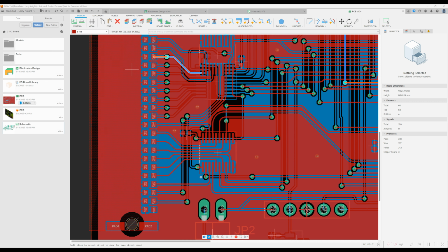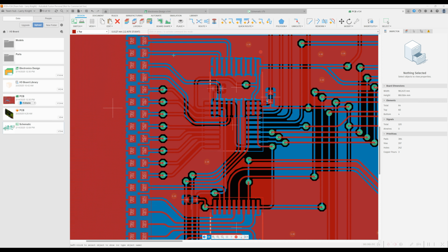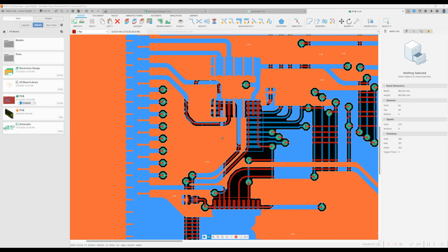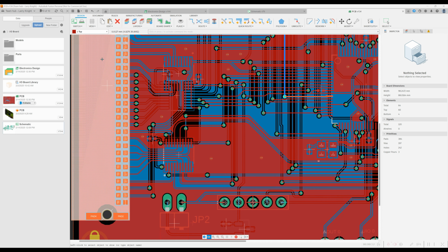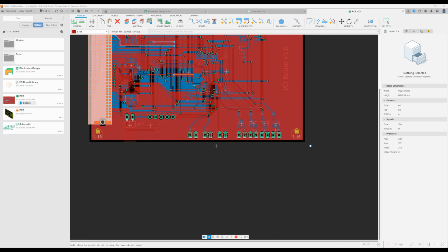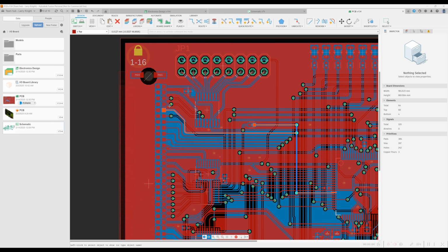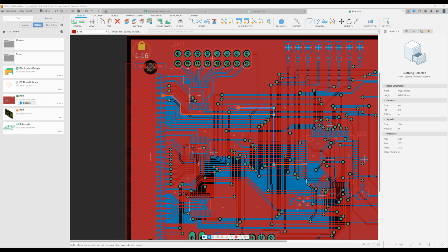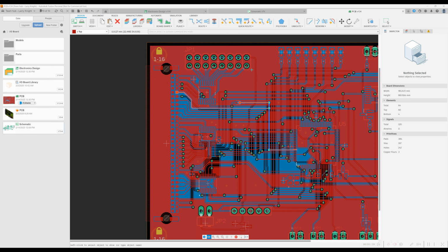And then for the data, I think it would be okay not to worry about these if we just measure these. So I've got an idea. What we'll do is take a resistor, put it on a piece of wire, and tie it to VDD. We will deselect this to a different address other than A0, which will deselect these chips and put them in the high impedance state.